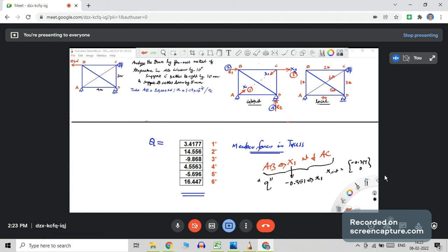But for that, you should know the principle behind flexibility analysis. What is the principle of flexibility analysis? You have already studied in previous semesters and this semester also, SA3 also. The main principle is to start from a primary structure. That is, change the indeterminate structure into a determinate one. That is the primary analysis methodology that you should know.